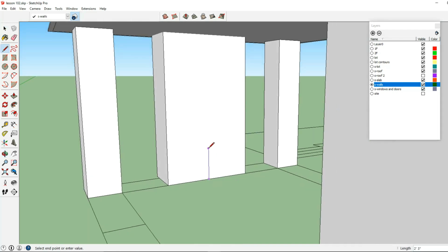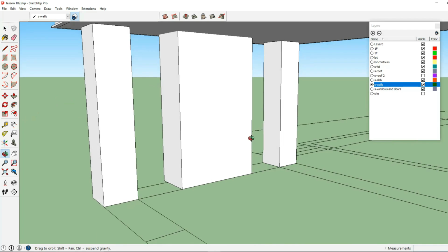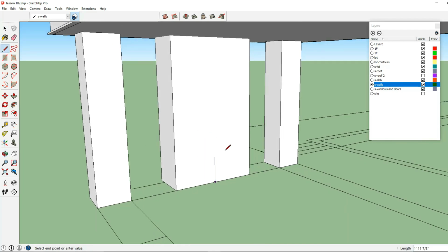And now let's create a fireplace area. Let's type 36 inches, and I want to create just a horizontal fireplace that's 60 inches long by 4 feet wide. Go down 16 inches, and let's go ahead and push that in.